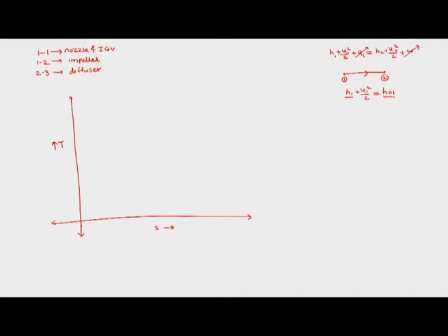We have in thermodynamics two types of terms, which are called static and stagnation. In thermodynamics we just know the static temperature, static enthalpy, static pressure. But when we account for it with gas dynamics, then we have to account for the kinetic energy associated with that static temperature, and if we add the enthalpy and the kinetic energy, then the resulting term would be called stagnation enthalpy.